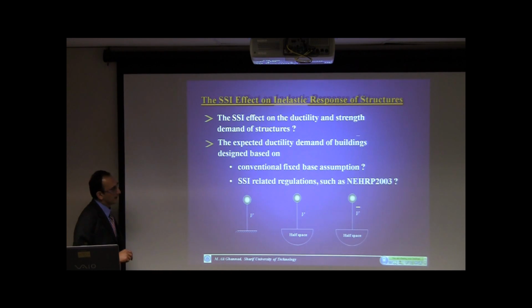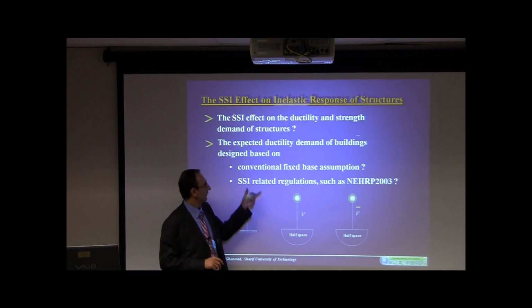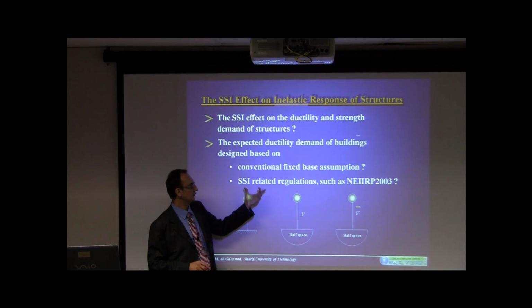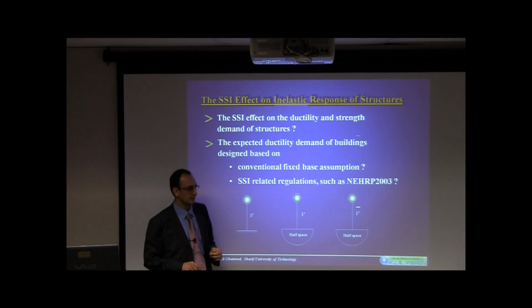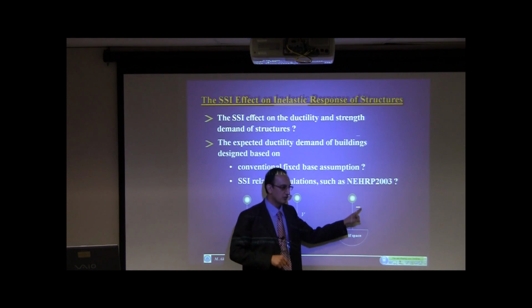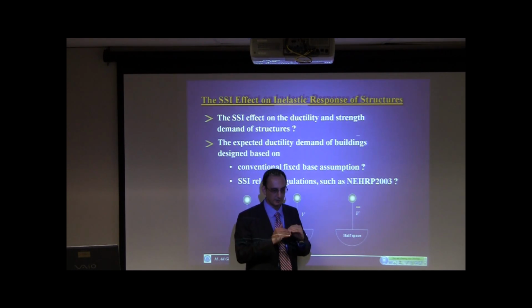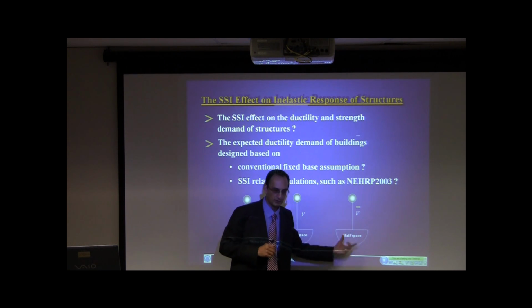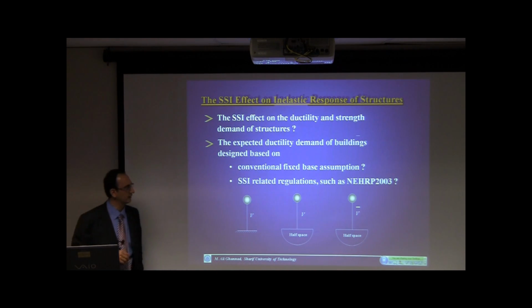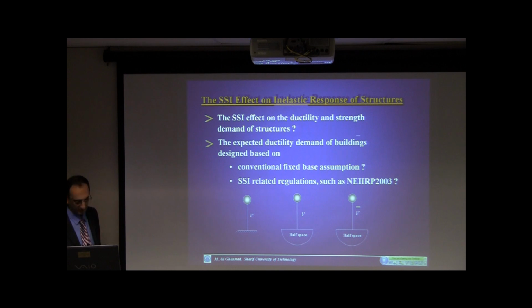And the response of those buildings designed based on the regulations like NEHRP 2003, because we reduce the base shear and design the buildings for a reduced base shear. So we want to see what the ductility demands and the strength demands are for these three cases.